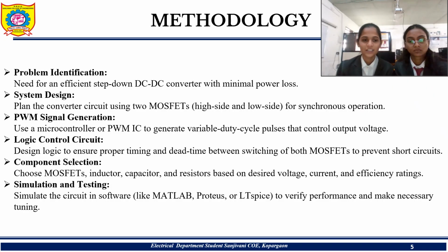Design the logic to ensure the proper timing and dead time between the switching of both MOSFETs to prevent short circuit. Component selection. Choose the MOSFET, inductor, capacitor, and resistor that will decide the voltage, current, and efficiency rating. Simulation and testing. Simulate the circuit in software like MATLAB to verify the performance and make the necessary tuning.